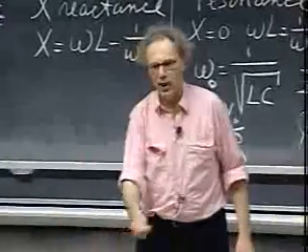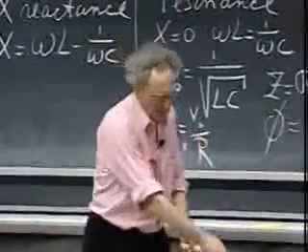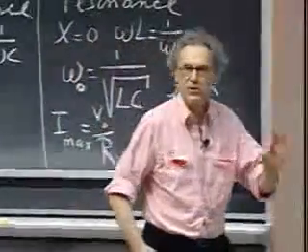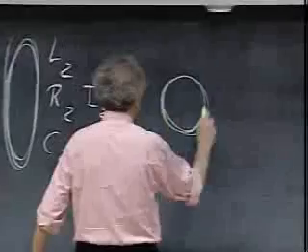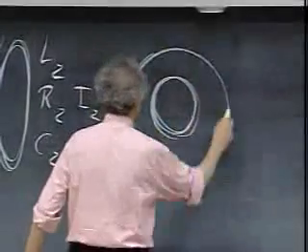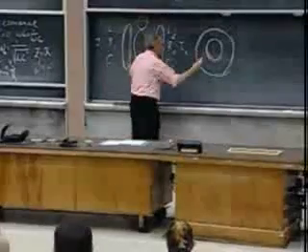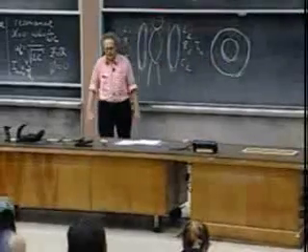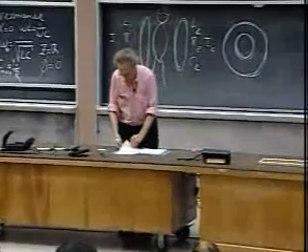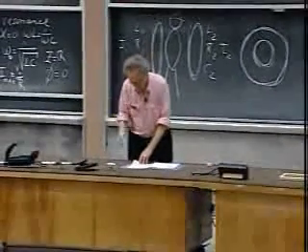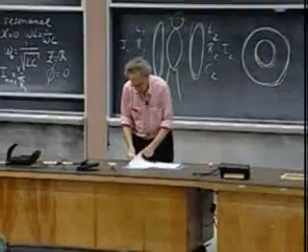When I was a kid, I went often to the beach in the Netherlands, and there were often people who were using these metal detectors. They were looking for coins. And those metal detectors, basically the same idea. Always two coils. This is this coil, and this is this coil. And when metal comes nearby, you have a system that goes off resonance. You get a difference in magnetic coupling between the two coils, and the system goes into alarm.